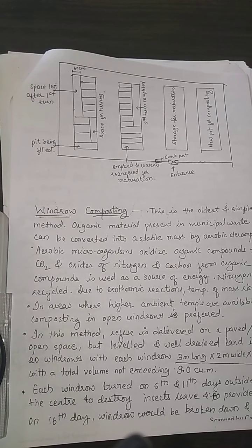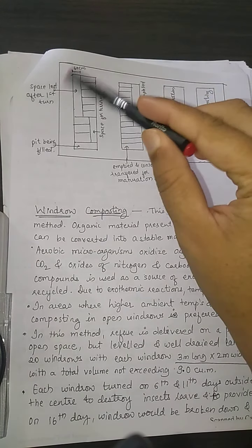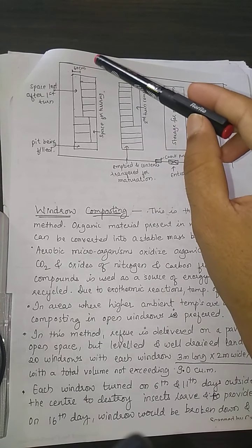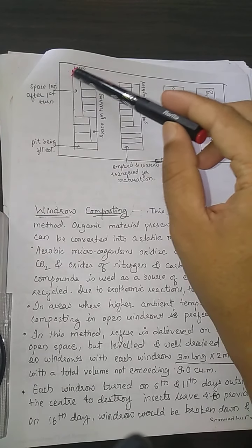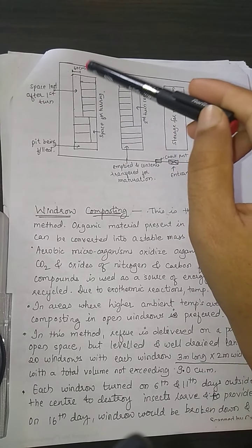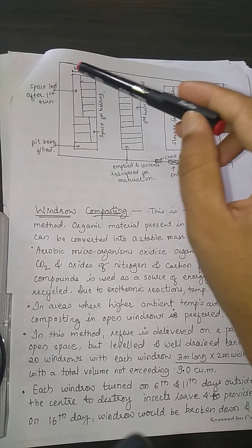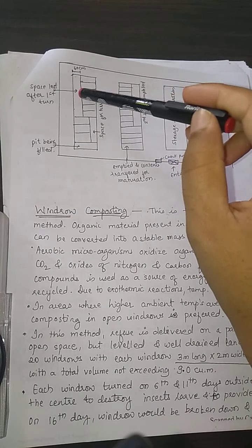Aerobic composting we call the Indore method. You can see that we have kept a space here. Also, we will be creating a pit. Inside these pits, the mixture of soil and night soil will be added, and we will be keeping a 60 centimeter strip open. As it is aerobic composting, we should have the turning of the municipal solid waste again after a few days.